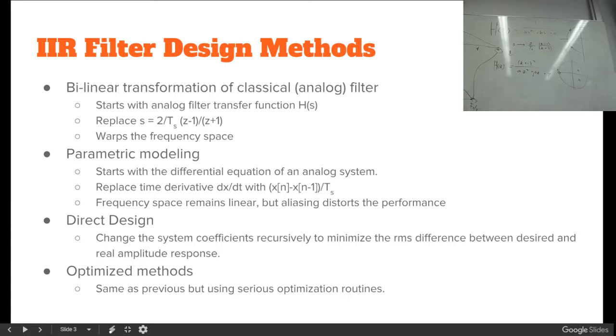So bilinear transformation doesn't have problems with the aliasing, since it takes the infinity frequency and puts that one to fs over 2. But this one actually, if there's some information that our sampling rate does not cover, then of course that information is aliased into the spectrum.